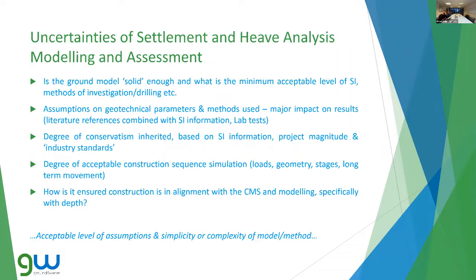Next we'll talk about the settlement and heave analyses. Firstly, it's regarding the amount of SI that we do. Is it acceptable? I know different boroughs have different numbers of boreholes that are required to be drilled. And is there enough information? Sometimes if you have limited access, you might not be able to get a more powerful rig to drill through really dense gravels and find the clay, and therefore you wouldn't be able to install a well and properly assess the groundwater, which could lead to encountering groundwater when you're excavating.